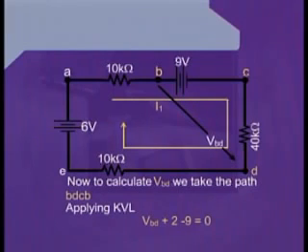plus, as we reach at the point D, we will be looking towards point C. While looking towards point C, we can see that there exists a resistance having a value of 40K ohm in between the points C and D. And we have just calculated in the previous slide that the voltage drop across this 40 kilo ohm resistance is minus 2 volts.